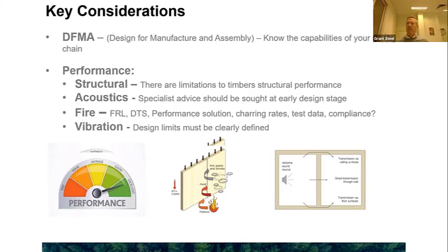So you want to avoid air gaps, service ducts, and shared elements across two tenancies. The manufacturer should be able to advise on the acoustic performance of the CLT panels with different floor and wall builds easy enough. And should also be able to provide you with tips for mitigating the flank transmission as well.